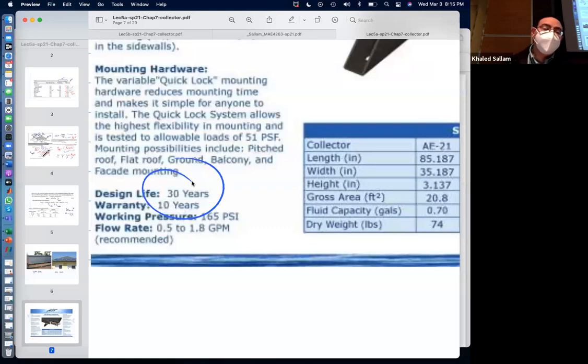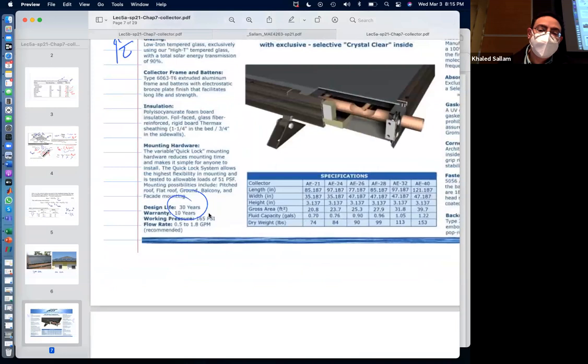And the lifespan of the heater is important, because a solar water heater will not cost you electricity during its life. You're just sitting there, taking the sun, heating your water. But how is it fair to compare it with an electric heater that sucks electricity from the grid? It's always the price per the levelized cost of production of those things. So levelized cost of water, for example, if you are doing desalination. So you want to see after 30 years, assuming this guy really lives, I mean, the warranty is 10 years, so I think we should base it on the warranty. So if the warranty is 10 years, then this guy needs to pay back his cost in 10 years. After 10 years, we assume he has no warranty, then he can fail on us.